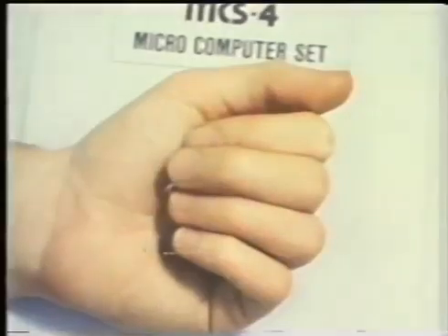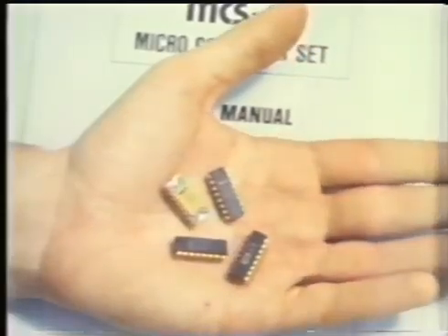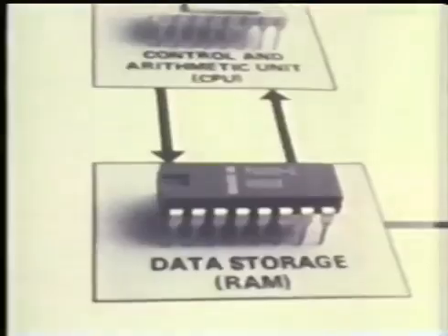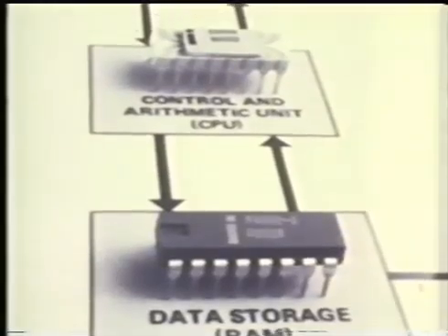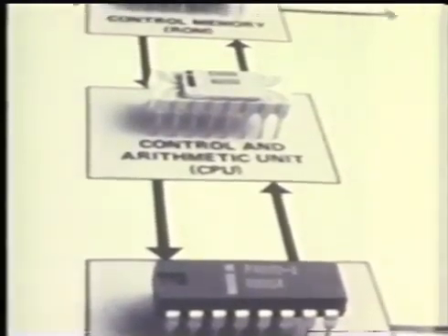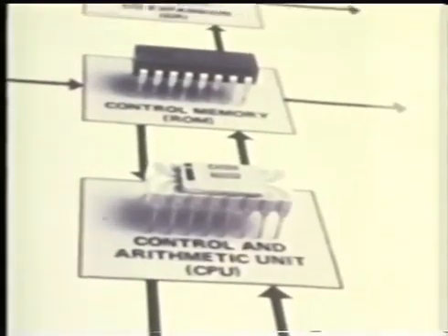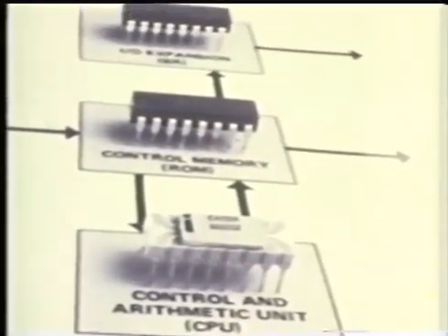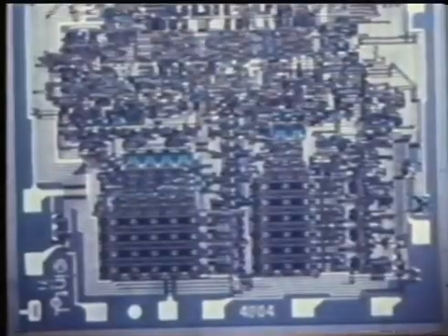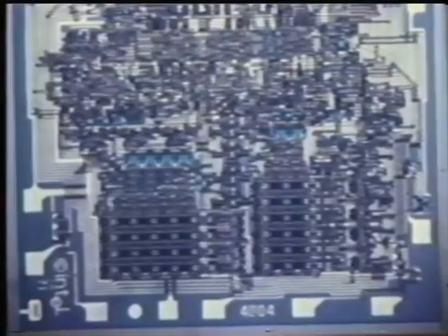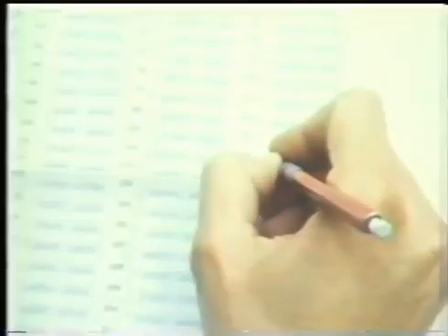The MCS4 microcomputer set is a family of 4 standard LSI chips with which you can build any number of powerful, proprietary general-purpose computers. The heart of the system is the one-chip 4004 CPU. You use only one of these 4-bit CPUs for each system. It performs control and data processing functions under the guidance of the microprogramming you build into the read-only memory.